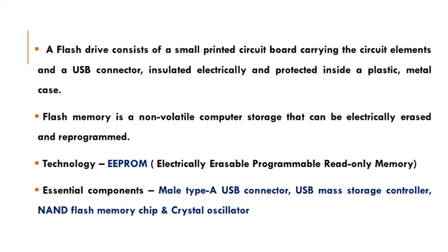Then we have the technology used in the flash drive, in which the electrically erasable programmable read-only memory, which is the EEPROM, is used in the technology behind the flash drives. Then we have the components of the USB flash drive, which includes the major parts: the male type A USB connector, then the USB mass storage controller, then the NAND flash memory chip, then the crystal oscillator. So these are the major essential components of the flash drive.